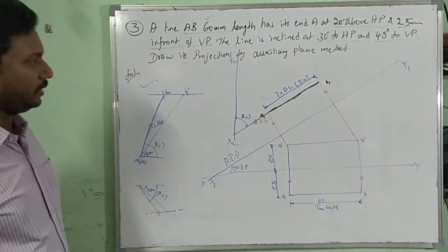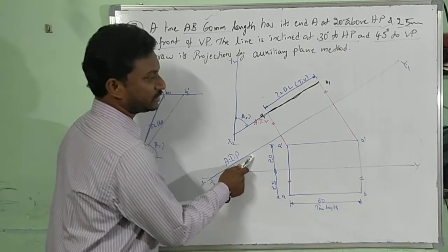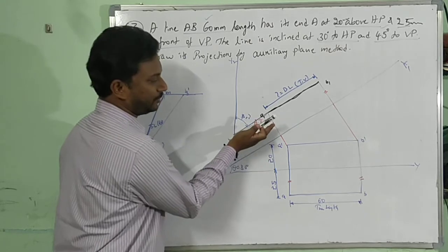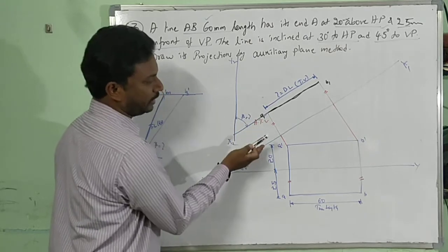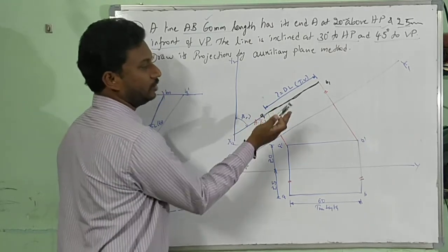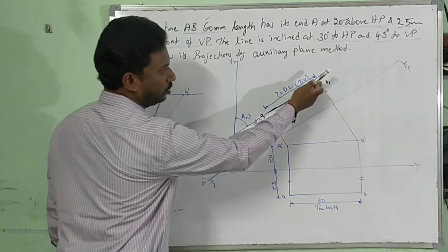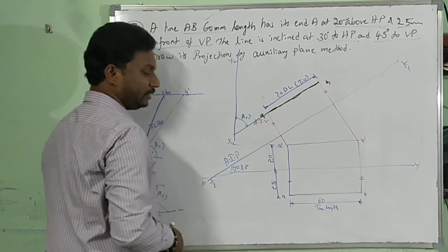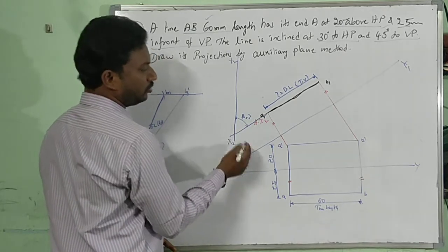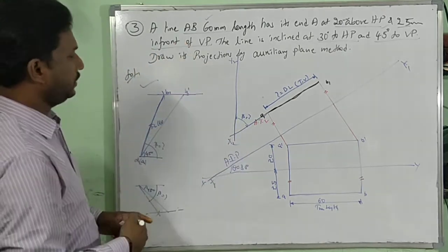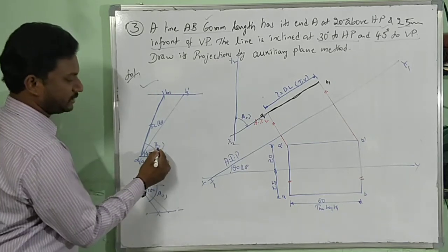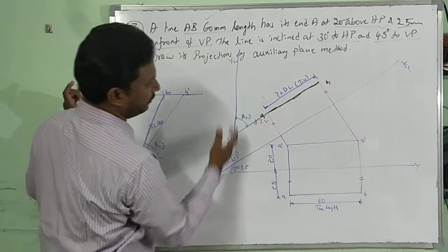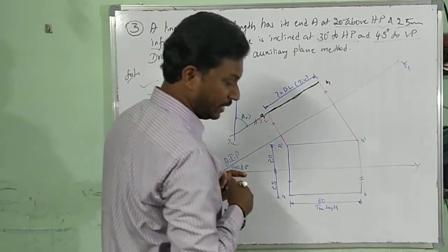Hope you all understand. See, for this x1, y1, I have to draw x2, y2. But there is a gap, right? You cannot draw it directly. It will be intersecting. So for that reason, you have to extend the diminishing length, and for that line, try to draw your x2, y2, right? Now it will be some more angle. If beta is 45, it will be around 70 or 80, right? Somewhat, you maintain that angle here, right?